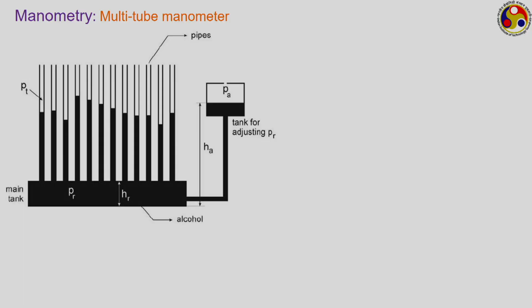So, the manometers, quite often in industrial applications you will find we keep on using multiple manometers, also sometimes called multi-tube manometers, where instead of one we need pressure measurements at different positions of maybe the same pipeline or same channel. In that situation we just have a common arm of the manometer connected to a certain reference. Like in this case, this is the standard reference arm which is open to the atmosphere, thereby maintaining the reference pressure as the atmospheric pressure.